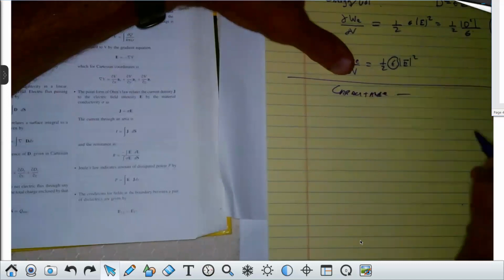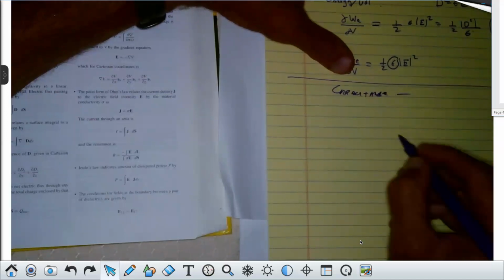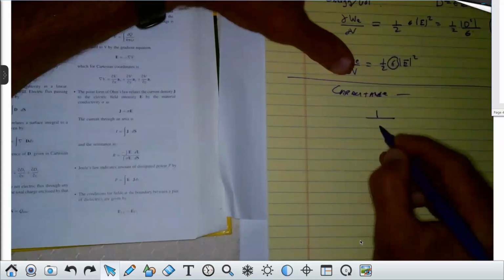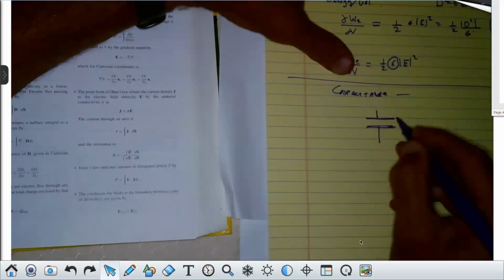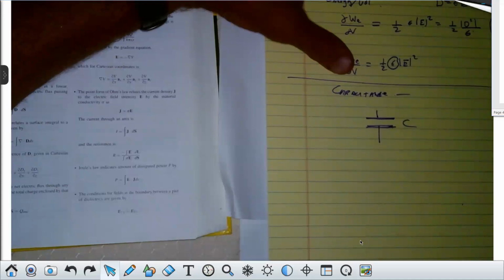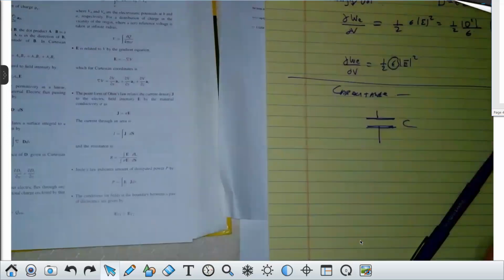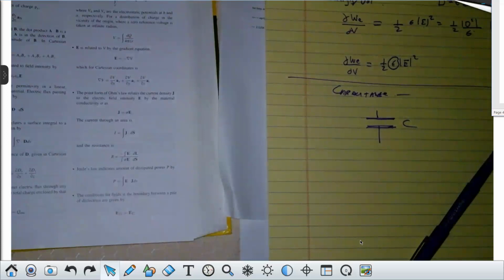what we usually do is start by showing a symbol. And a capacitance is just 2 parallel plates. They usually show it like this. This is your circuit's example of what a capacitor was, right? What a capacitor really is, is any 2 conducting surfaces. And they could be planar plates of metal, it doesn't matter. Any 2 surfaces, you can have a differential voltage across them, and that means they'll support plus and minus charges on either side.